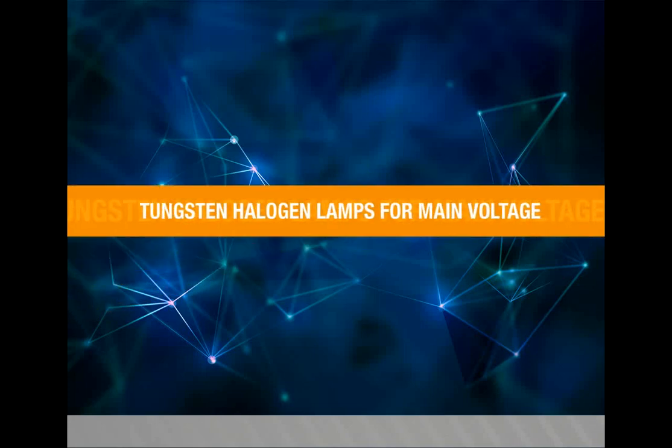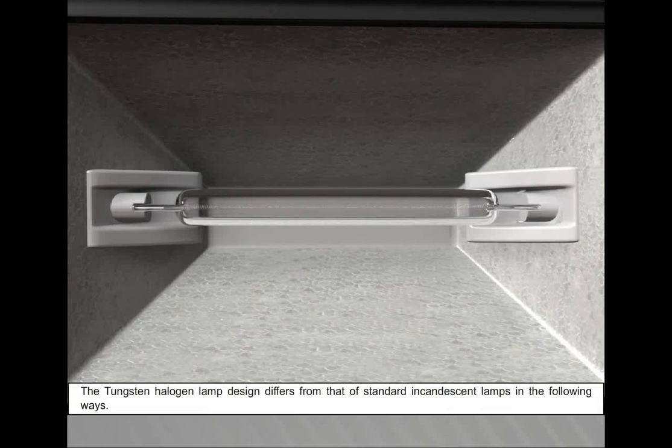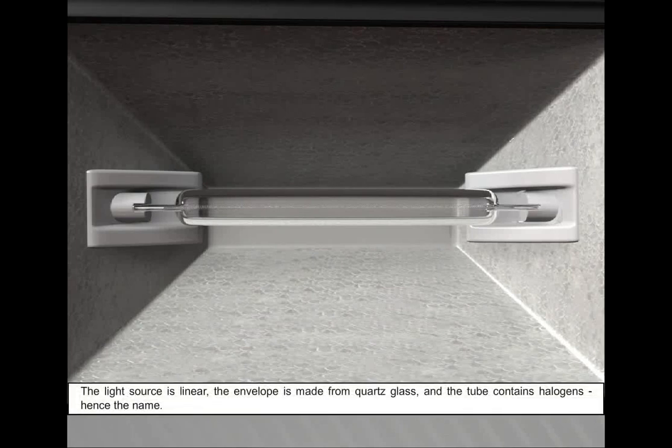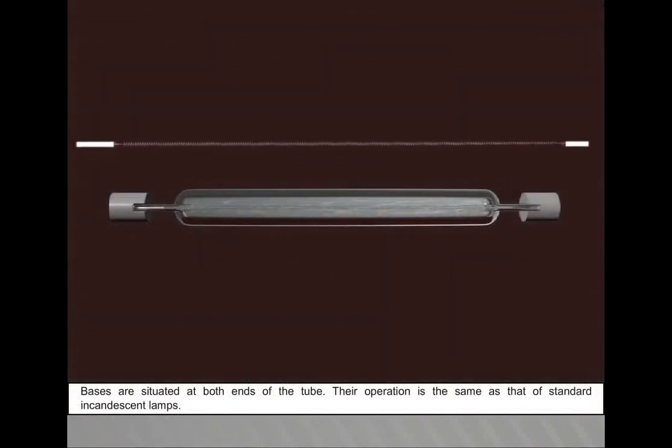Tungsten halogen lamps for mains voltage. In this video, we are going to see about tungsten halogen lamps for mains voltage. The tungsten halogen lamp design differs from that of standard incandescent lamps in the following ways. The light source is linear, the envelope is made from quartz glass, and the tube contains halogens, hence the name. Bases are situated at both ends of the tube. Their operation is the same as that of standard incandescent lamps.